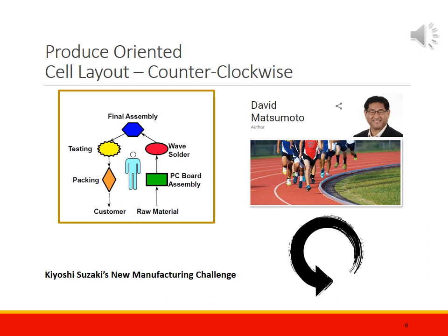You can do that with your left hand. It takes no dexterity. In fact, a super user is going to be taking the part with his left hand, not even looking at it, just sending it down the chute. The next operation is already underway with the right hand and the part in the nest. That's why cells run counterclockwise, because most of us are right-handed.